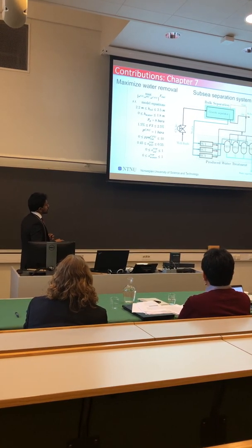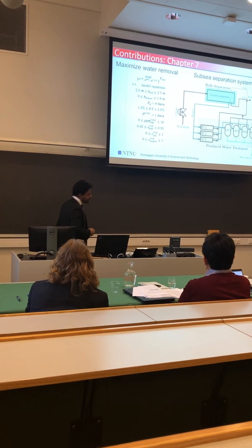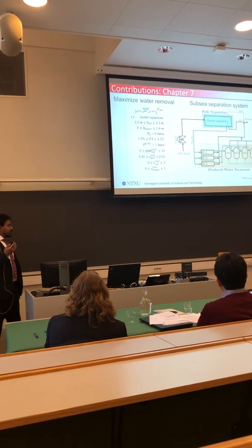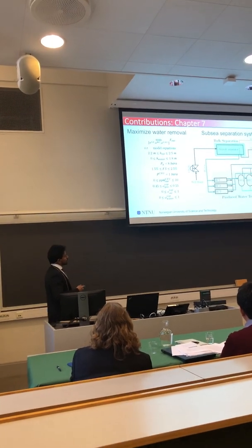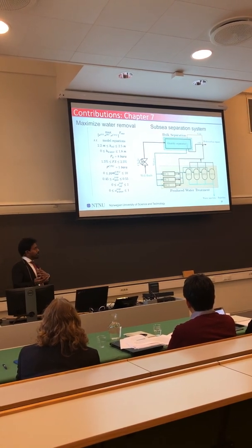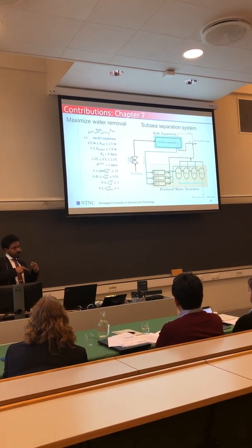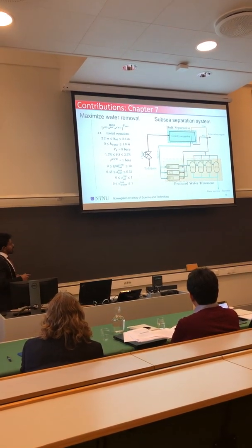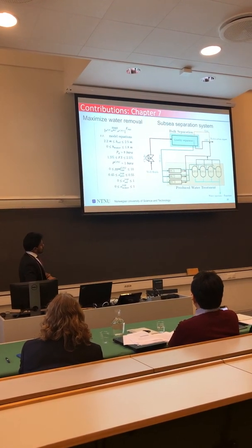The gas holdup in the reject stream here is considered to be between 45 and 55%. The reason why we chose these numbers is that to be able to control something, it needs to be able to be measured. Here we make an assumption that the gas fraction measurement is possible accurately only between 25% and 75%, and to keep a 20% margin for those times when, because of imperfect control, it could go beyond the set point for a while, we keep it between 45% and 55%. And we have the other physical constraints also.